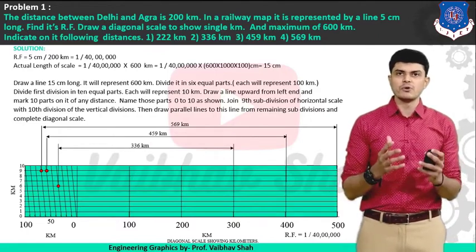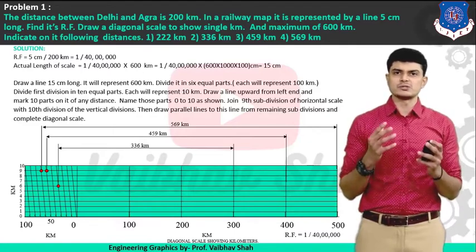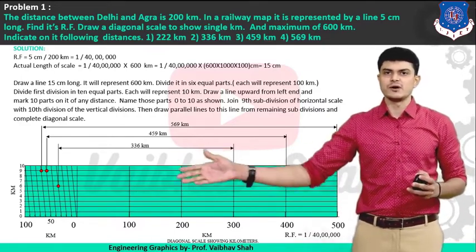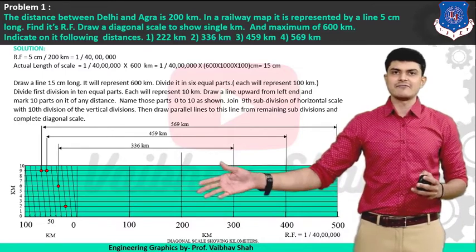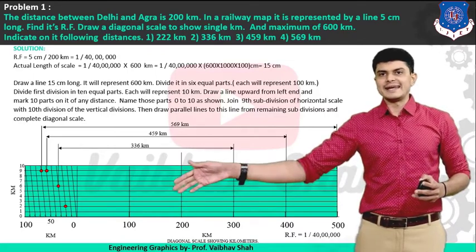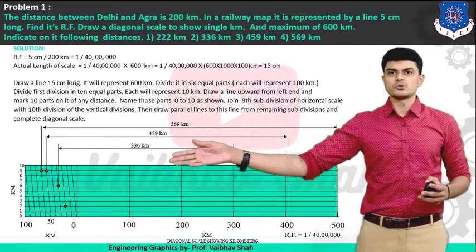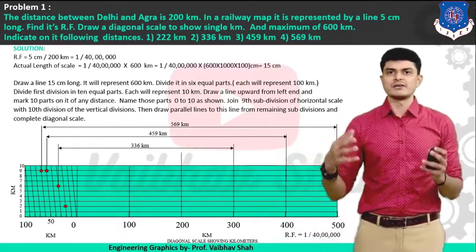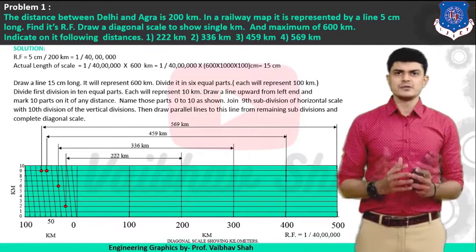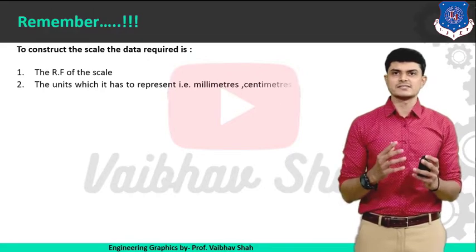After that, let us see one more example. First one, 222. So 222 can be broken into 3 parts, 200, 20 and 2. So let us start with 200 on this primary scale. So 0, 100 and 200. So let us draw one vertical line. After that, 22, that means we have to go on the secondary scale. So 0, 10 and 20 on the left hand side of the secondary scale, and after that you need to go by 2 steps up. So 2's horizontal line and 20's inclined line would give you a red point, and which is nothing but your 222. Very easy.